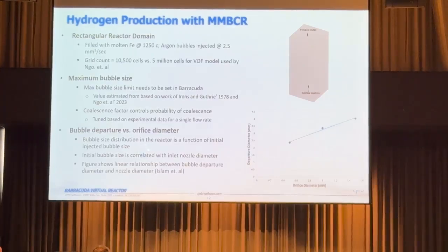And there's actually a lot of work published here where there's a relationship between the size of the bubble and the size of the nozzle through which you're injecting the gas. In this particular case, I used the work by Islam here, and so you can see a relation between the diameter of your nozzle and your departure bubble diameter.